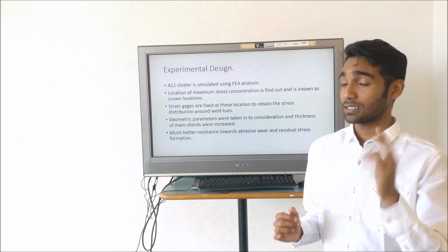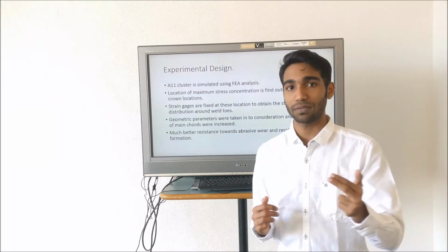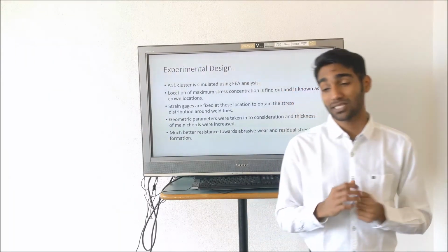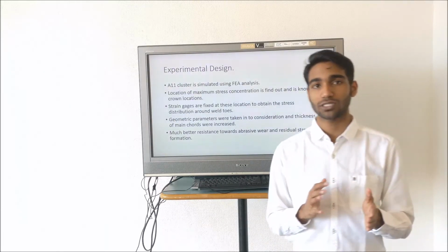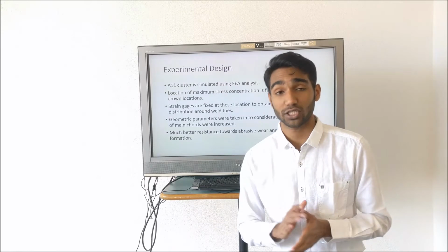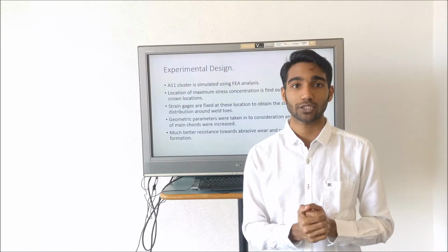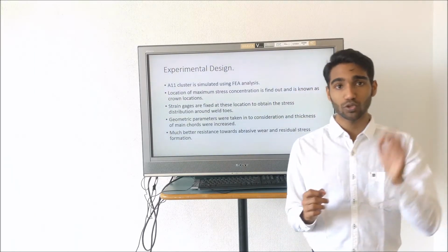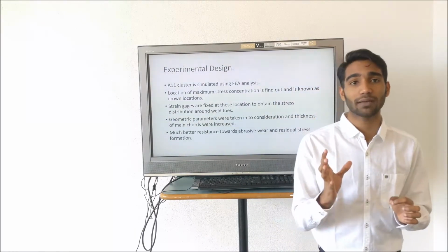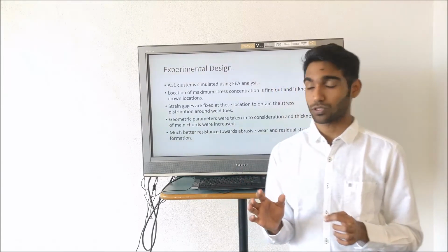And the geometric parameters are varied to obtain the optimum design feature. By changing the main core diameter and keeping all other parameters constant, a significant reduction in the residual stress was obtained, and this was made part of the actual design. So the new design consisted of a new sleeve and an increased diameter of the main core thickness. This was a major feature of the new design proposed.